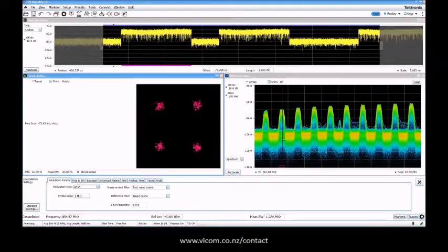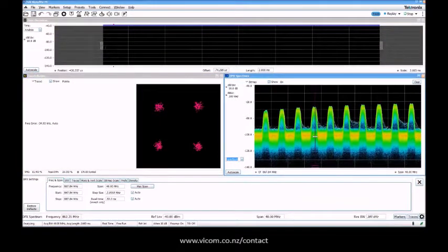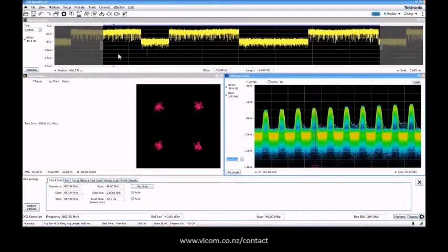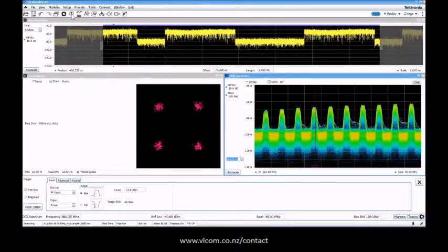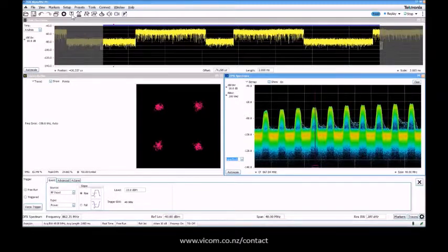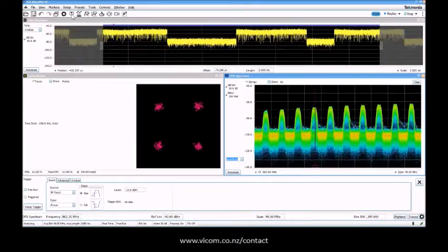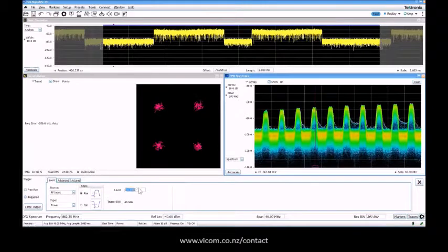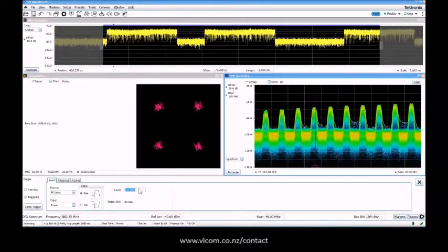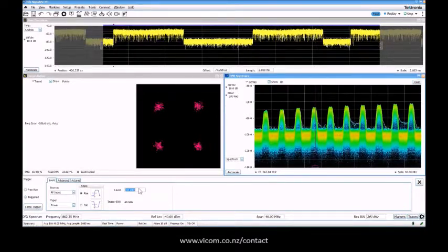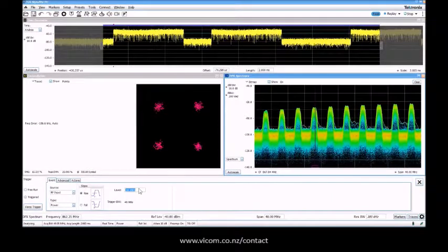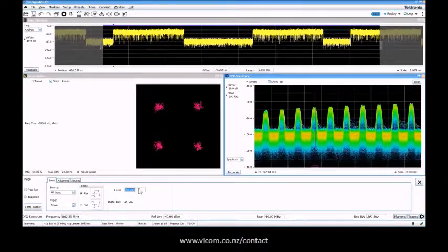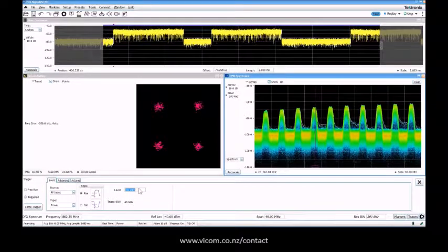Second thing, I'm just free running here. Second thing is you can move along this again. And lastly, I know this video is a bit fast, but lastly I will add the triggering, because the triggering gives us some features to look at. We know that every second burst has some problems. So if I go here for triggered, and I just move the trigger down to like 55 or something, I should have a more stable trigger, hopefully. Yeah. Not really. Okay, at least there's something.